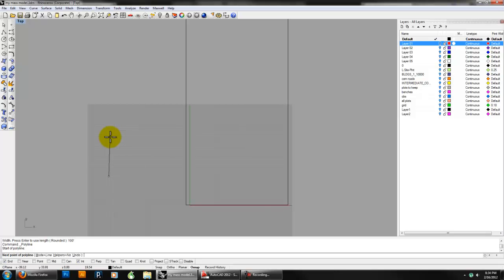If I wanted the relative coordinate, let's say I want a line that is 50 foot tall, I could say R for relative, 0, 50 foot, so moving the Y, and then I could say next point, I could say R 25 foot, 0, let's do that, okay, and to finish it off, I could say R 0, negative 50 foot.